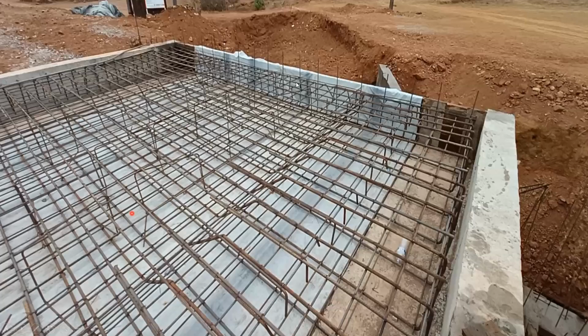Again it is a crank. Okay, so I'll show you this in a deck slab when I go for further videos, but right now what you can identify is that it's a kind of crank what we have given. That means your bar will come from here. Okay, like this, it will bend, it will come, they have got a crank here, and it will go in this direction. Okay, it will go up to here. Similarly in the other direction, you'll bring one more bar from here. Yeah, your bar will come like this.